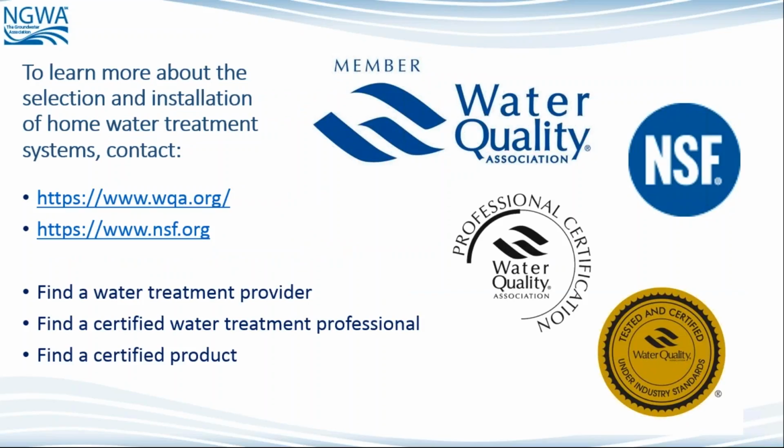So looking at that, how can we handle the problems of iron and manganese? Number one, if we have an existing well and we know or can find out that certain zones are producing the higher iron and manganese, we can basically line the well and block off those areas of flow. Number two, if we're considering a new well and we do our homework and know the hydrological and geological issues in that aquifer, we can design and construct the well to alleviate the available high iron and manganese concentrations. And number three, we can install the proper water treatment systems within our home to alleviate the problems.